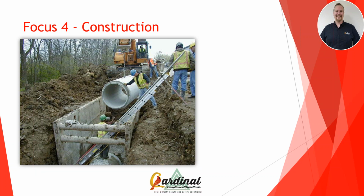All right, how many of y'all identified that fall hazard with the gentleman in the blue hard hat? So let's do some math real quick. I can't tell you off the top of my head how tall that trench box is, but let's assume the gentleman in the green hard hat is only 5 foot tall. Now, he's standing on a culvert there that is probably about a 4 foot outer diameter. So now we have 9 foot. It's kind of a judgment call here, but from the top of his hard hat, I'm guessing we have at least another foot to the top of that trench box. So we're looking anywhere from 10 to 12 foot.